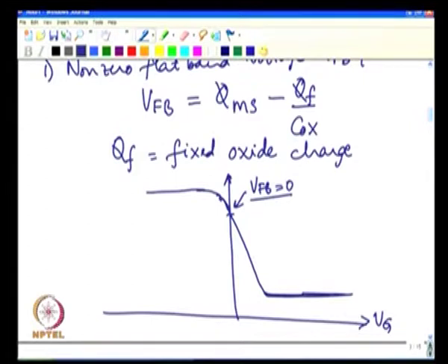One important thing that you want to recognize here, the capacitance value at any gate voltage is uniquely determined by the surface potential in silicon. In other words, when you have the accumulation condition, if you recall, if I am looking at a p type substrate, and if this is my oxide interface and this is my p type substrate, what will happen? I have an accumulation region which is this. If this is EF, bands are bent up like this, you see, correct.